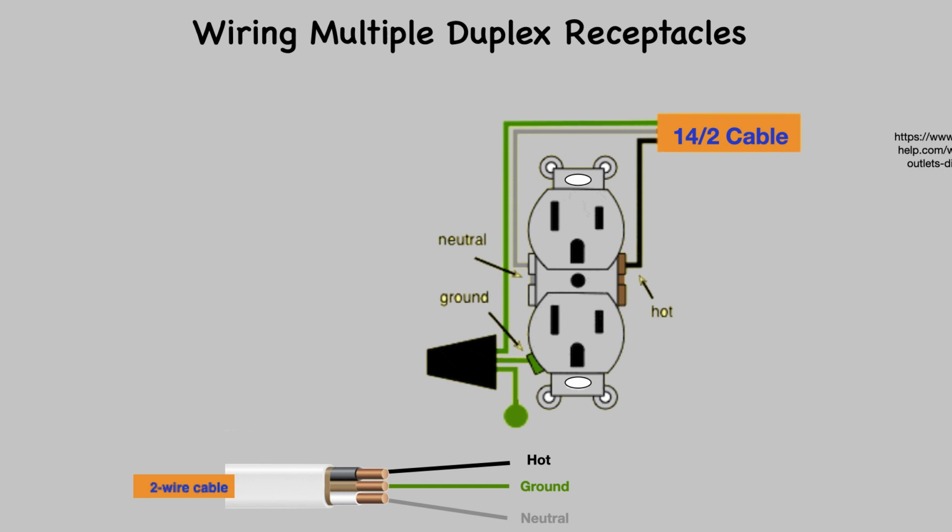This is a standard 15 amp 120 volt wall receptacle outlet wiring diagram. This is a polarized device. The long slot on the left is the neutral contact, and the short slot on the right is the hot contact. A grounded contact at the bottom center is a crescent-shaped hole. Don't use this receptacle when no ground wire is available.